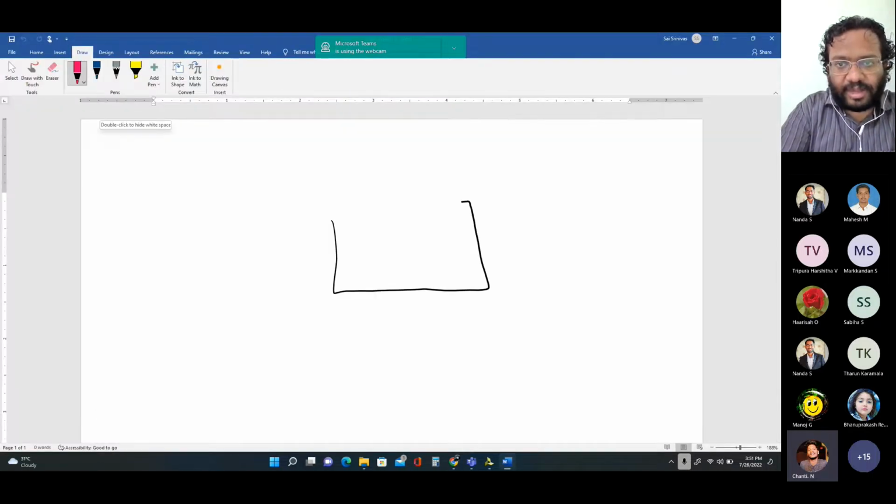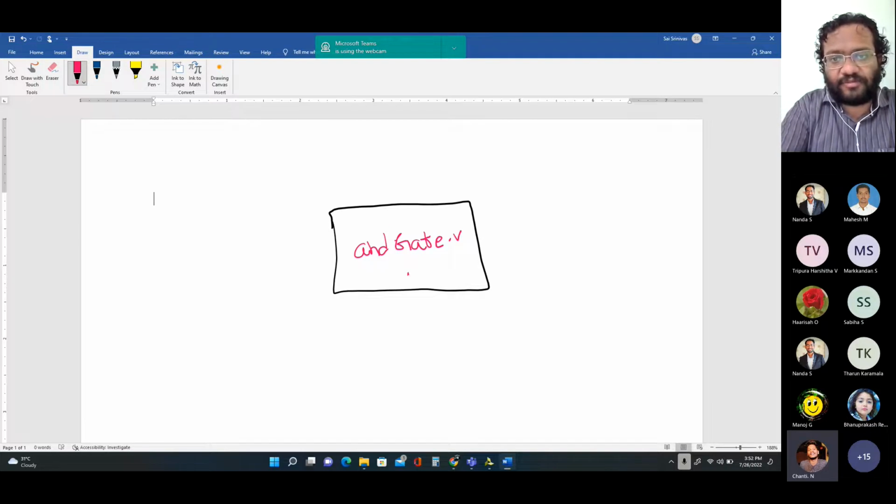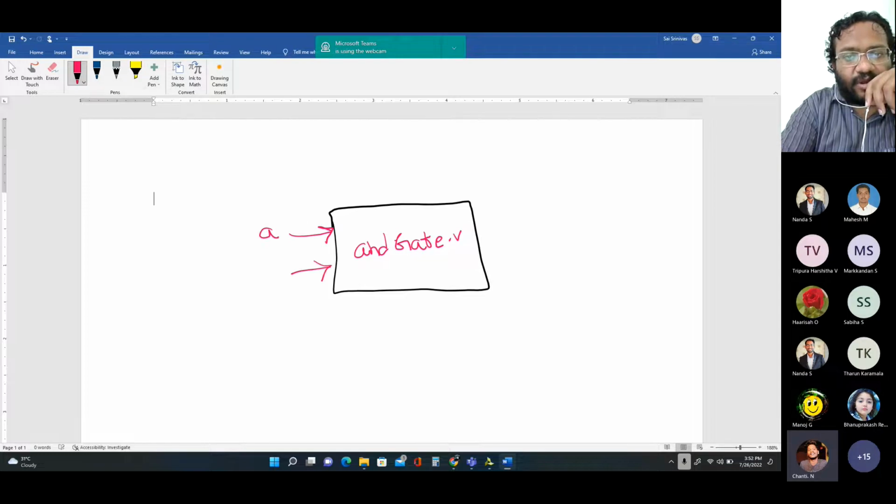So my black box is now ready. I named it and_gate, and the extension of this file is .v, that is Verilog. If you are working with VHDL, it will be .vhd. We are not dealing with VHDL, so Verilog, that is .v. I have given it one input A, 1 bit, an input B, 1 bit, and an output C, that is 1 bit. So my black box and inputs and outputs are defined.